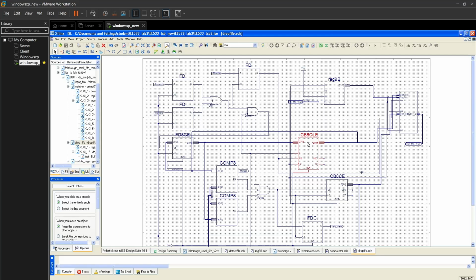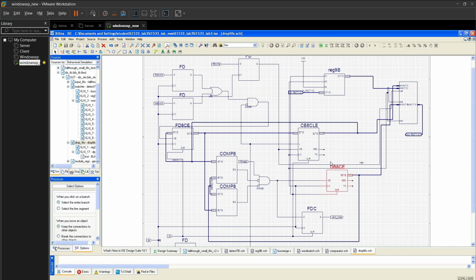Binary counters. So this will increment the write address based upon if a write operation is active, and similarly for read, this is the pointer for that. Binary counter for that. So this will just increment our write address and read address, which are our pointers in this case.